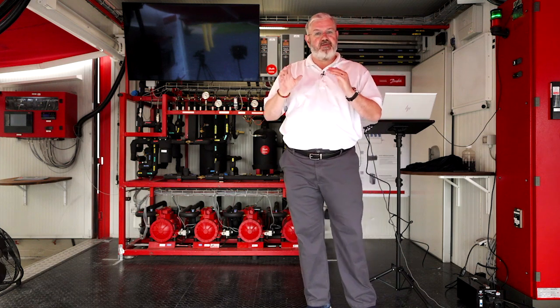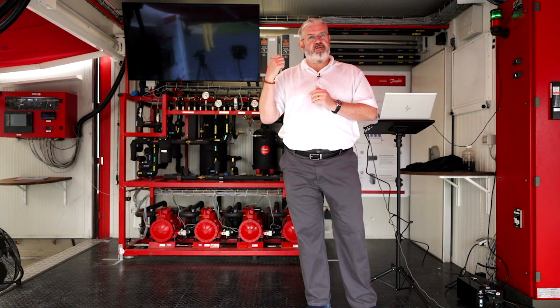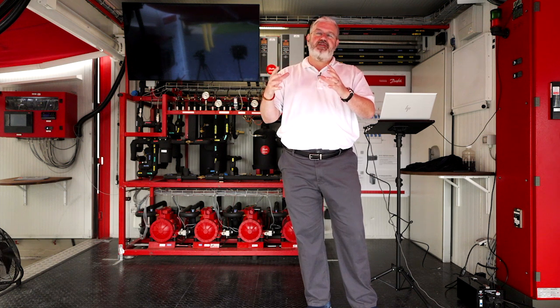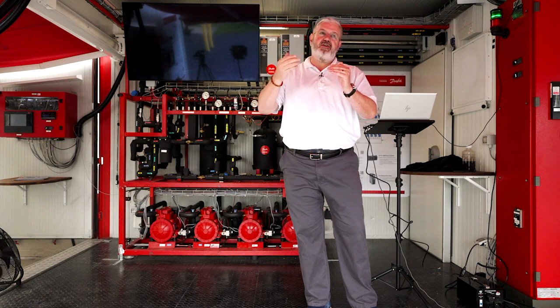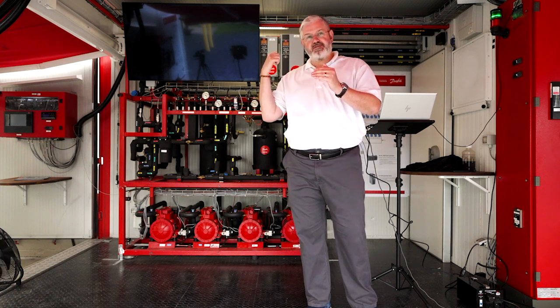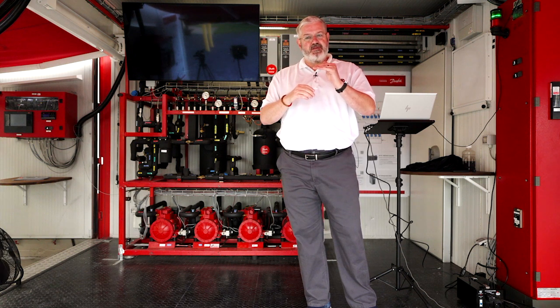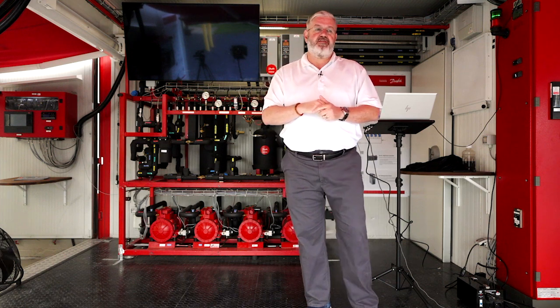So regardless of ambient, you're still going to have medium temp compressors discharging heat to the gas cooler. Let's say it's a block of ice up there. You're still going to be moving mass flow, able to build pressure because these are pumps. They move pressure. So your high pressure valve is going to limit the low end of a system, much like a drop leg regulator or your flood valve would do on an HFC system.